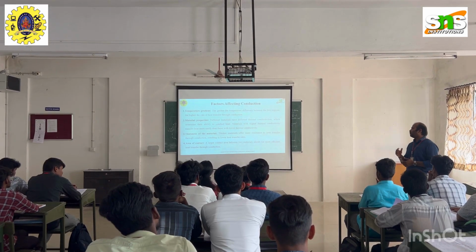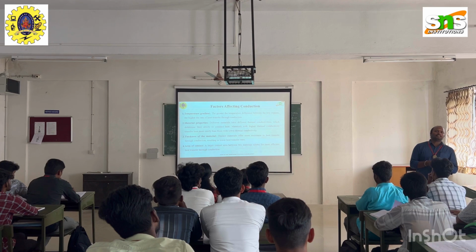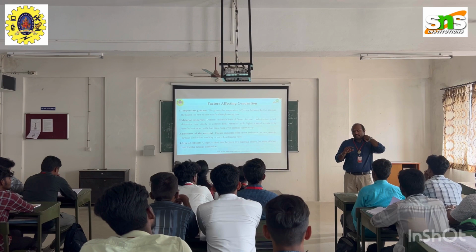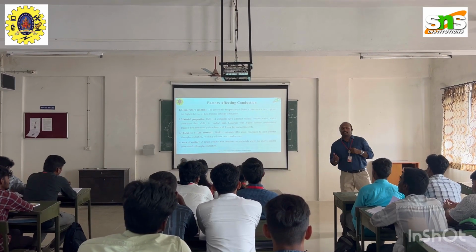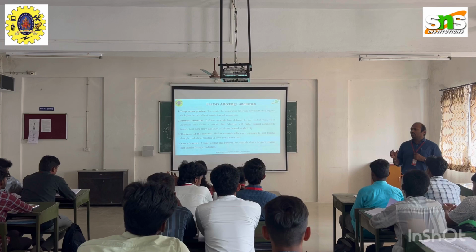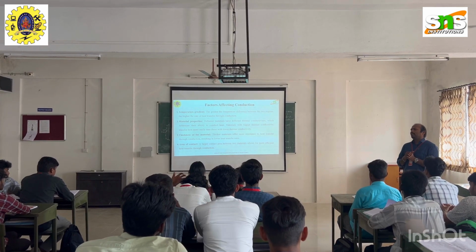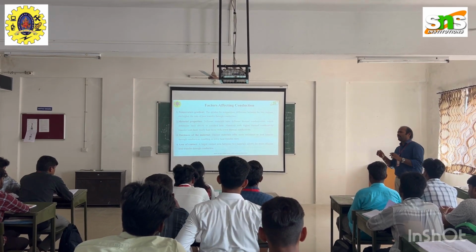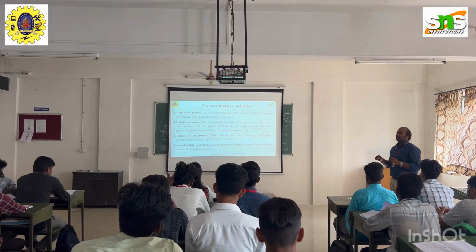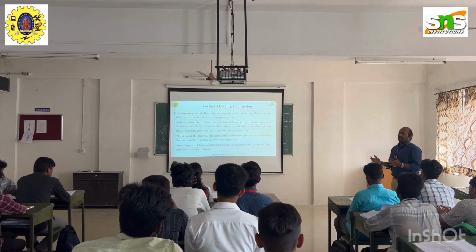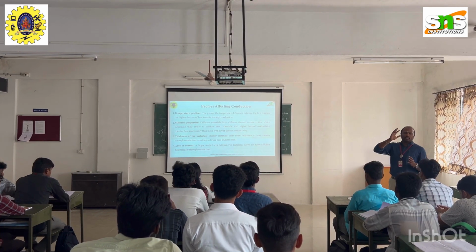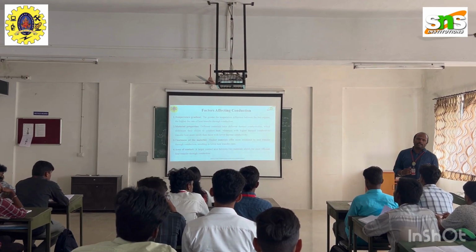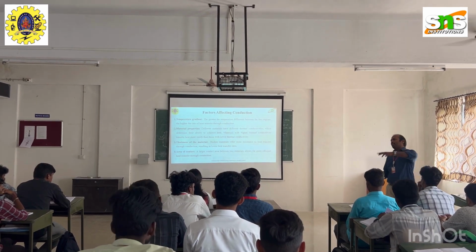The third one is thickness of material. If the material has very low thickness, heat transfers at a faster rate. If the material is thick, it takes much more time to transfer the heat. For example, in transferring hot metal from the furnace to the ladle, the thickness of the ladle is much higher. If the thickness of the ladle or mold is very minimal, we can't hold the temperature, and sometimes the ladle or mold can break due to the high temperature at the spot.